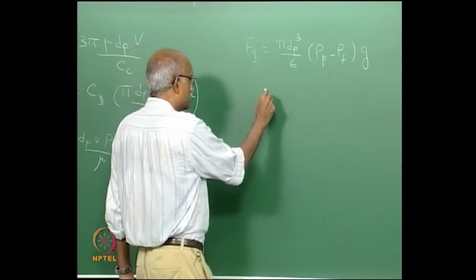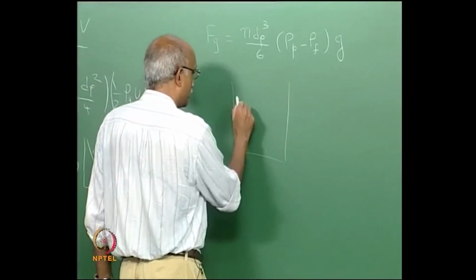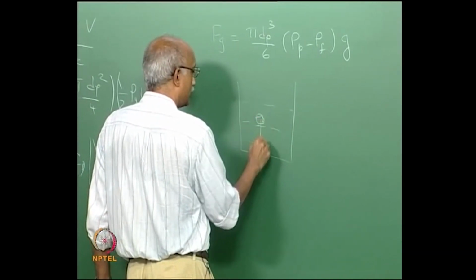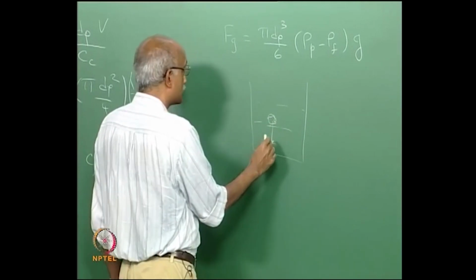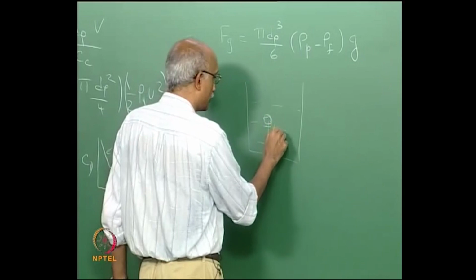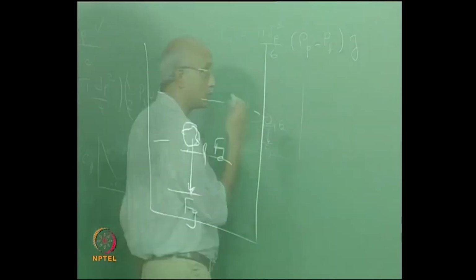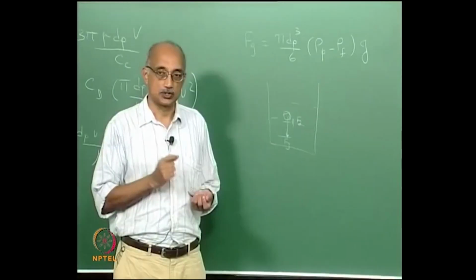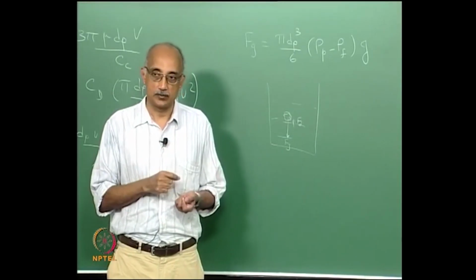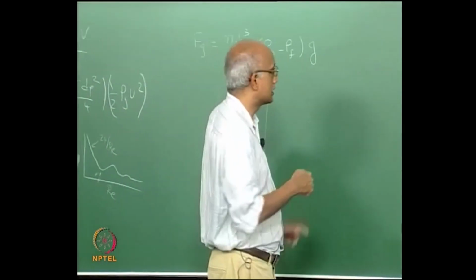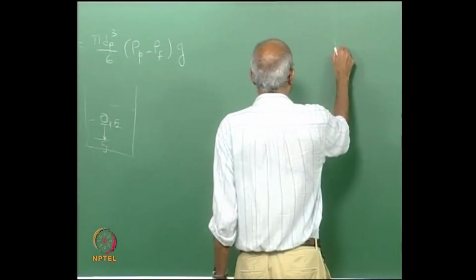Now, in the case where you have sedimentation occurring, where you have particles that are suspended in a fluid, the gravitational force Fg is acting in this direction, and the drag force is essentially opposing it, and because of that the particle reaches what is known as a settling velocity or a terminal velocity, and the expression for that can be obtained essentially by equating Fd to Fg.